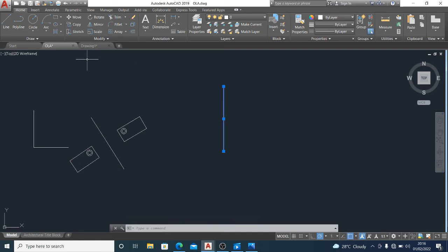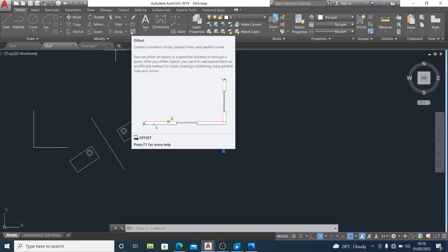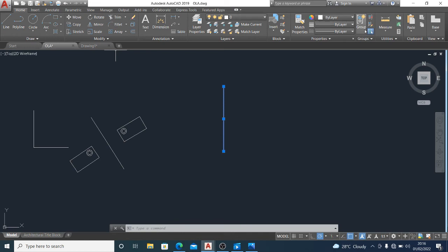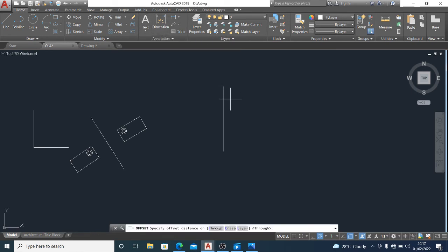you would either use, now I would create a particular tutorial where I can show you how to use certain commands. Yes, after this tutorial I'll do that. But now I'm trying to show you all the tools that you can see right on the bar. Now I'll use this tool, offset tool. I right click, left click. Then it asks me how much I want to offset, I have to specify my offset distance.